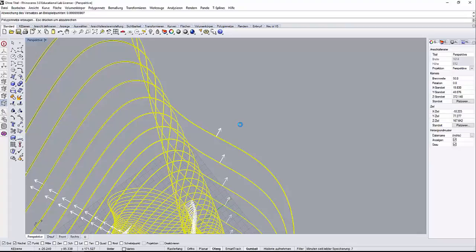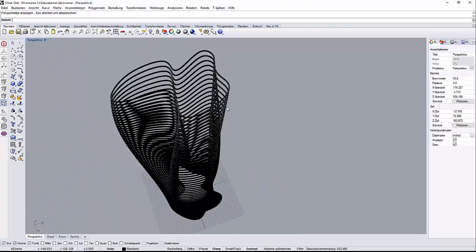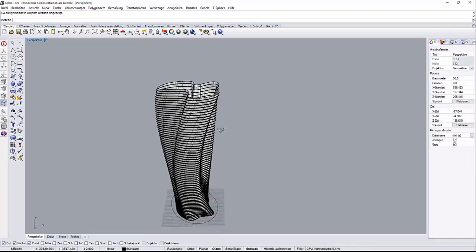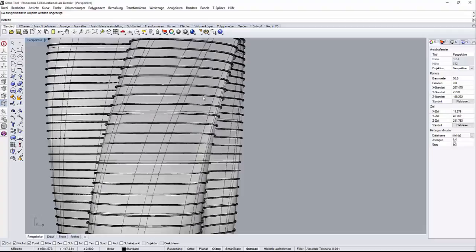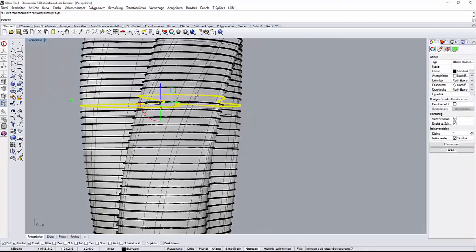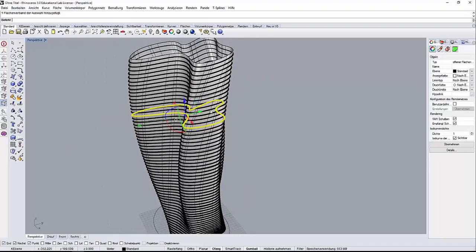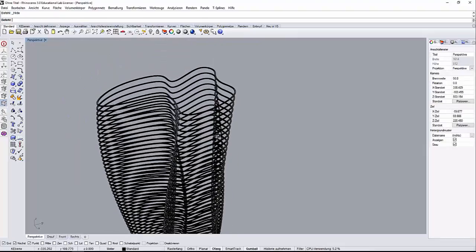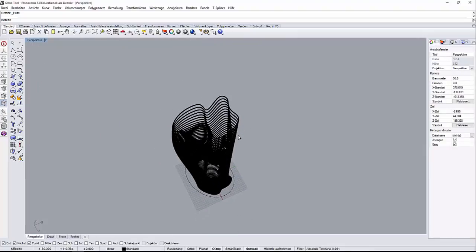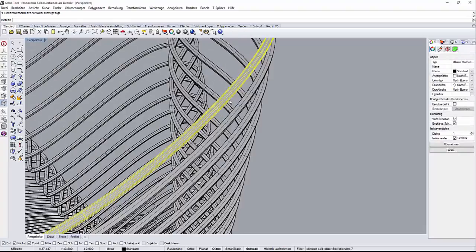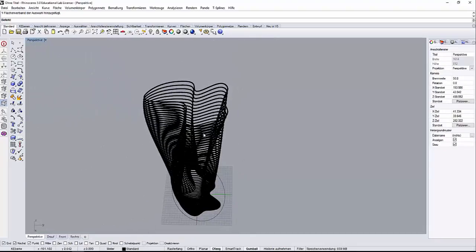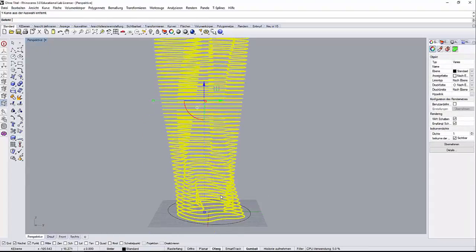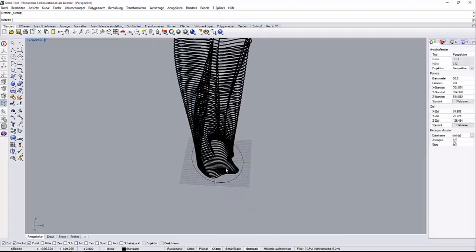It will take a little bit of time because there are 150 elements, but look at this, now we have a structure. If I bring back my element inside, now I have a glass facade plus some sort of rimming in it. Now one thing that I'm going to do, I'm going to hide this again. I'm going to select all these elements. Let me see if the group is hidden. Great. So I'm going to select all these elements minus the circle and I'm going to group them, Control G. So now all these elements are together.